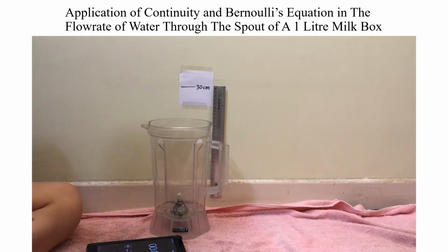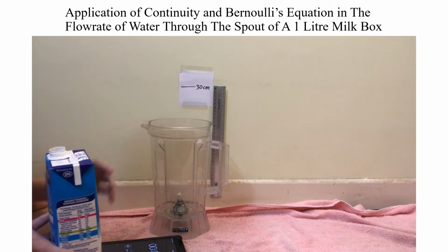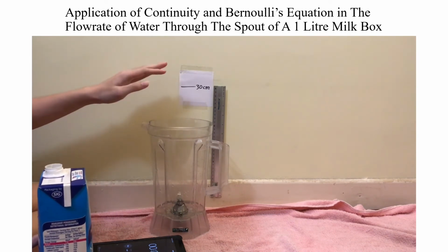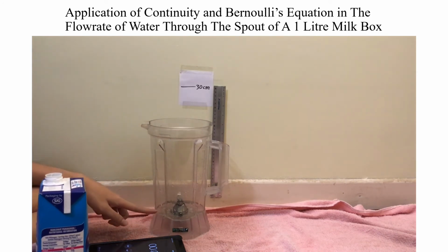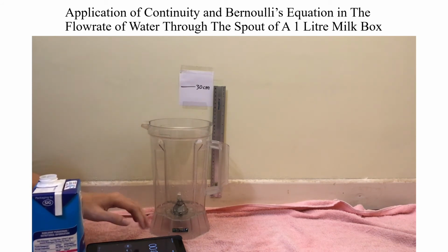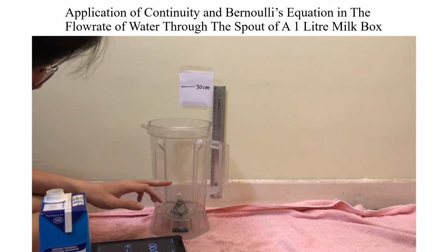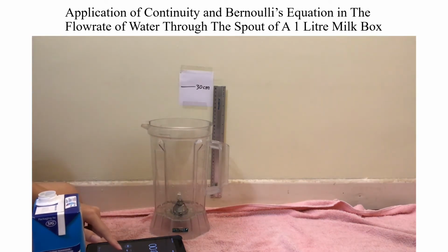So in order to do that, I'm going to place the milk box that is filled with 1 liter of water at an elevation of 30 centimeters, and as soon as I release the water into this accumulation tank, I will start my stopwatch, and as soon as the water level reaches 1 liter over here, I will stop the stopwatch.